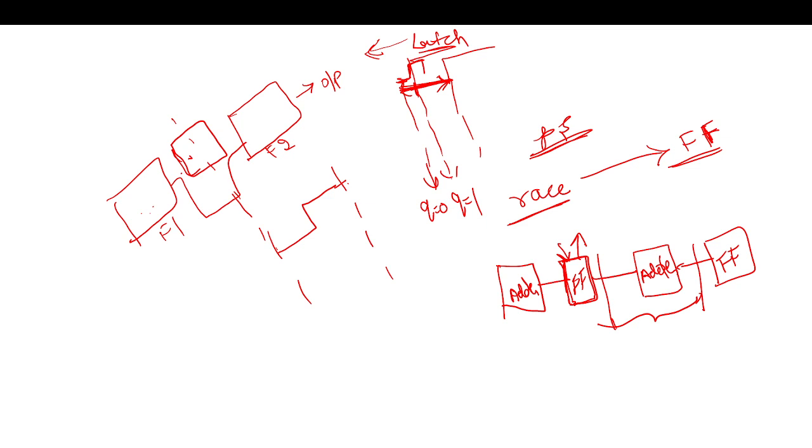Yes, with latches we will have the race around condition. That's why we go for flip-flops. Usually in designs we will have D flip-flops, and in counters we will have T toggle flip-flops or JK flip-flops. Mostly latches, I don't think we will be using for any other design.